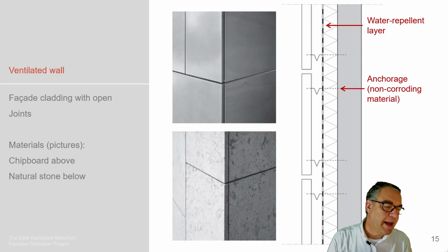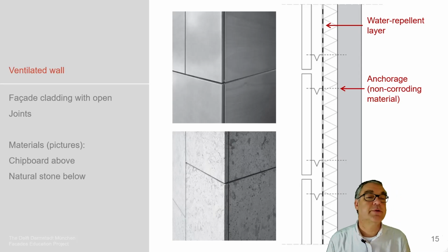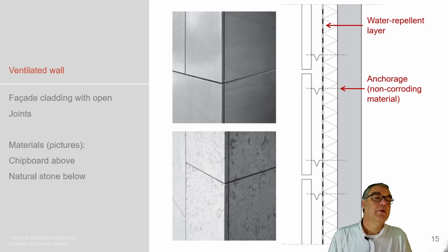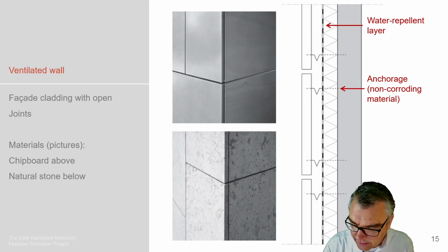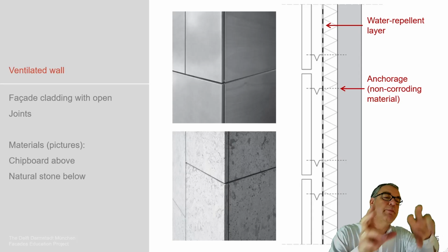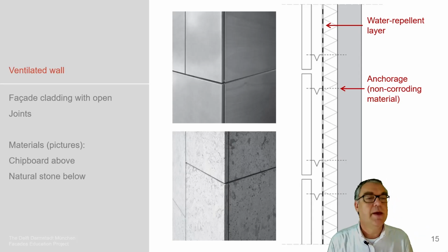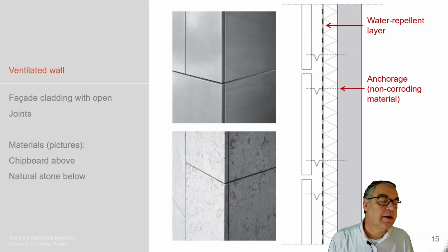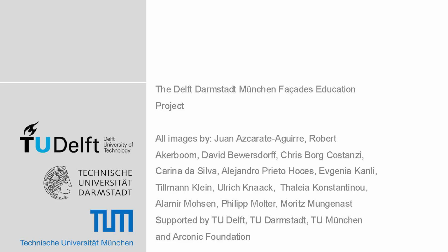You can imagine that certain materials require certain thicknesses of structure. And they all have to be brought back with their loads into the main structure, so they need to penetrate the breathable membrane to allow their structure's load to be brought into the system. But it does not penetrate the inner airtight layer, which needs to be entirely sealed and airtight as a system.